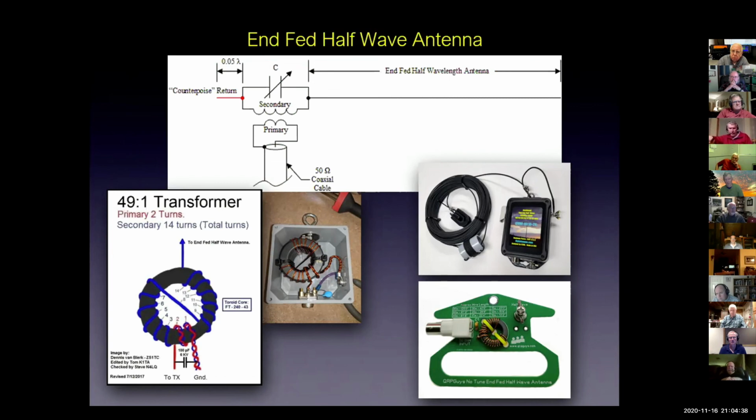His headphones and his paddle and everything that was connected to the radio in that case became the counterpoise. And as a matter of fact, he somehow got the thing detuned and wound up blowing up the final transistors in the radio because the SWR went through the roof for some reason.